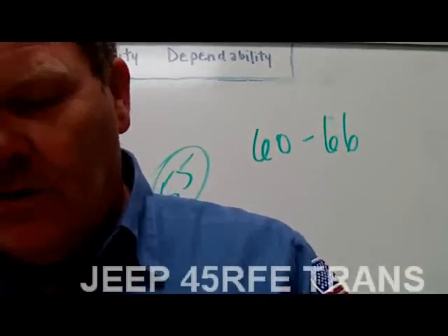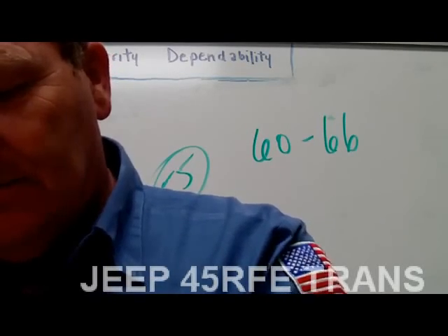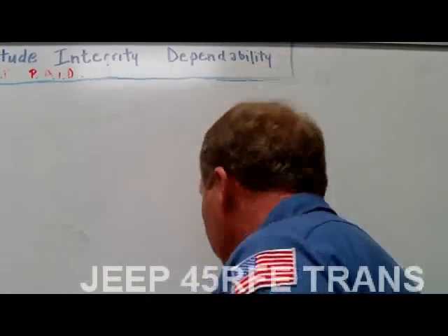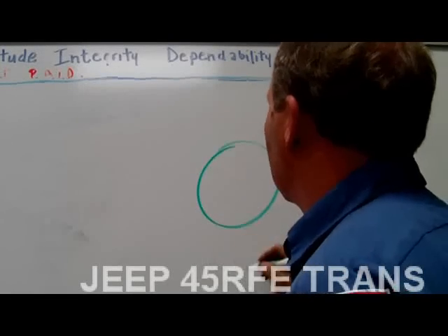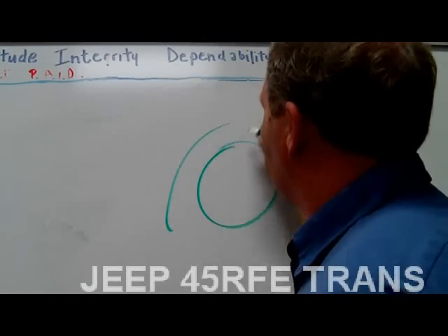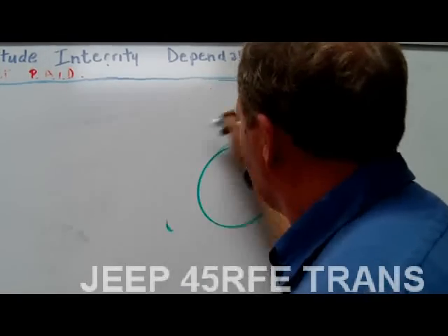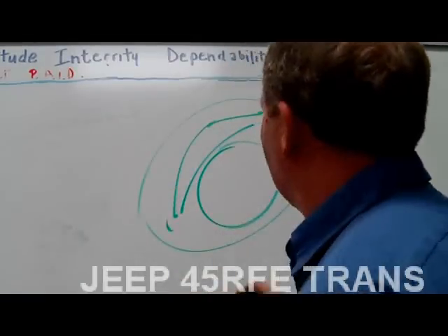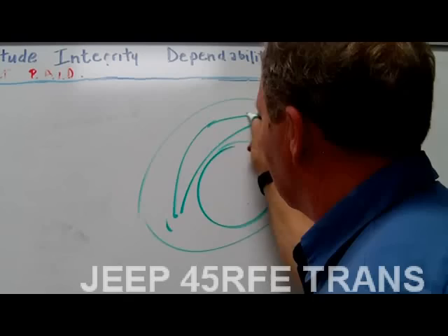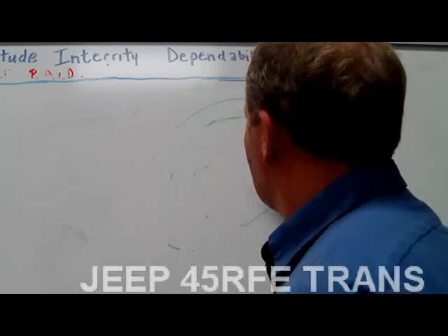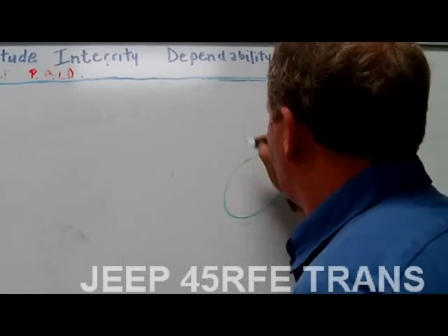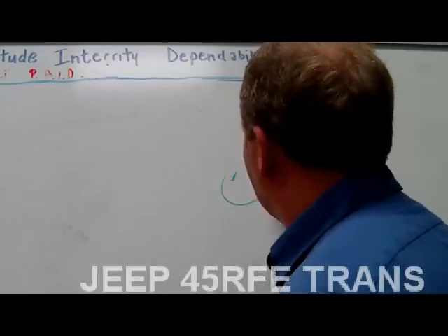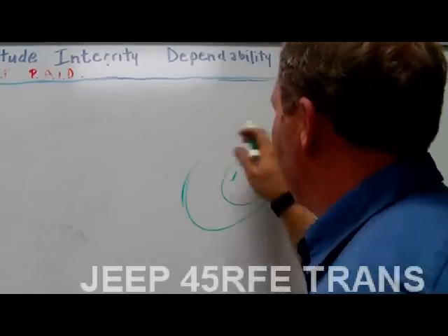The fluid pump is really cool because usually you'll have either a crescent gear that's got a little island next to it, and this gear will be driving an outside gear with a crescent between them. Or you've got your gerotor gear, which has a gear like that turning through.